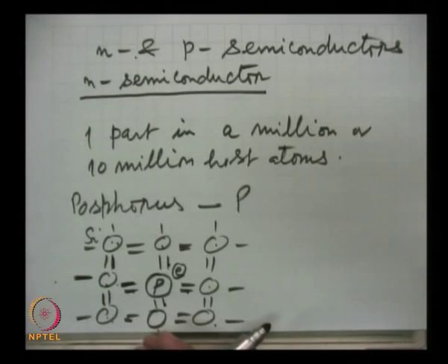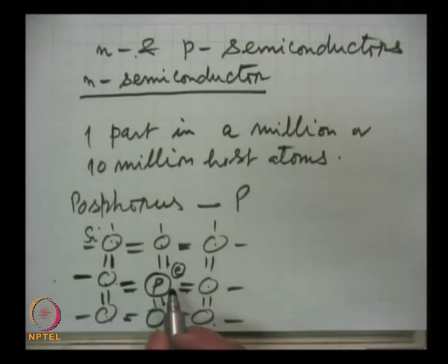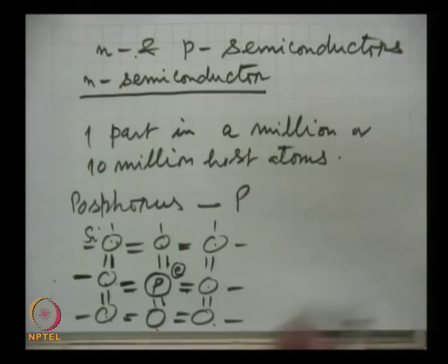So the dielectric constant, the permittivity of the material, will enter, and the real part of the dielectric constant for silicon is around 11.5, so the force on this electron from its parent atom phosphorus is reduced further by this amount, and it works out that